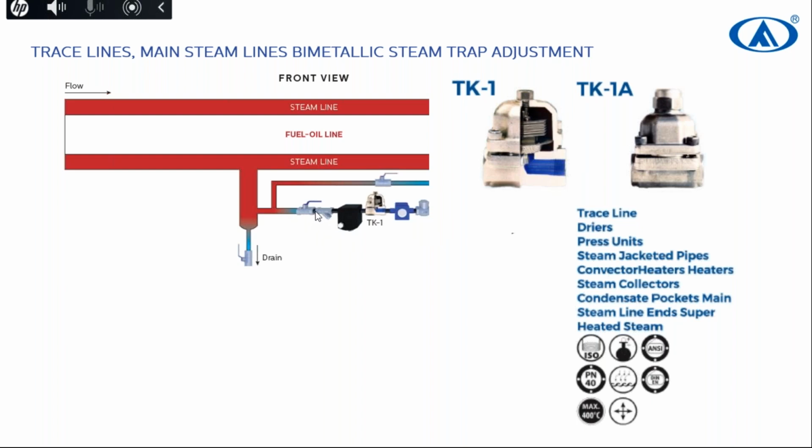What is the use of air vent in float type steam trap? As air ventilator, as air discharge, we are using the thermostatic capsule that I mentioned, which is H, S, and L, or we are using bimetallic element. We have both of them as an option.